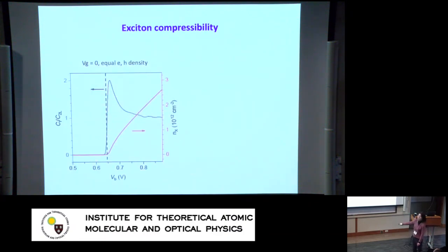And the black curve is one example. So in this case, we have equal electron hole population. I'm increasing my bias, nothing, until I hit some threshold. Suddenly, exciton is injected. And then if I keep increasing, then again, the peak goes away. It's like injecting electron hole, but they are dissociated. And I can integrate this black curve, get the density out. And using this method, we can inject the exciton up to 10^12 per centimeter squared.